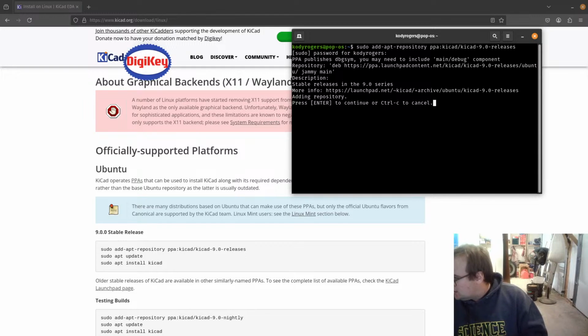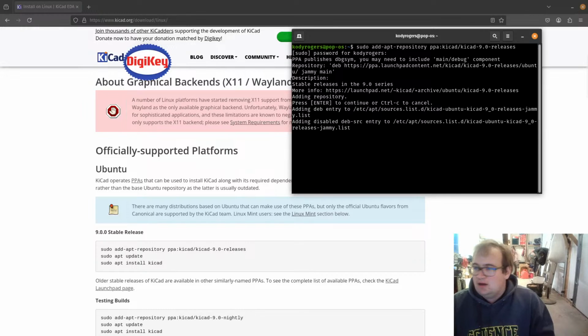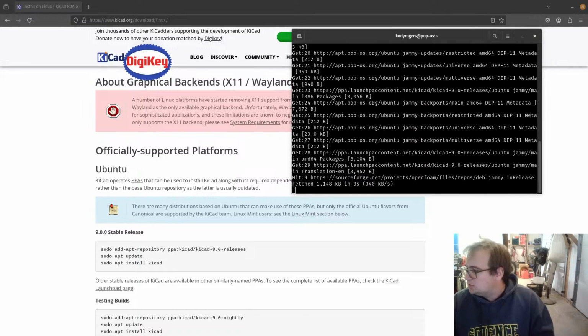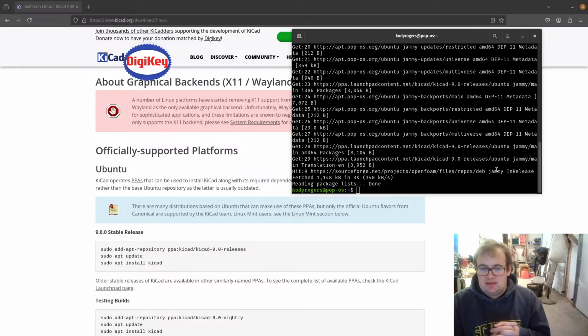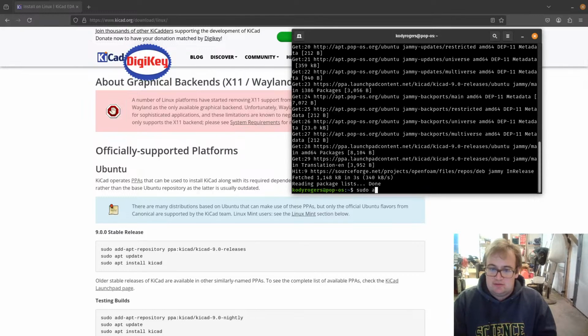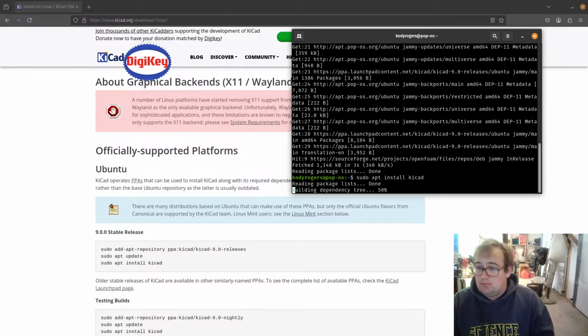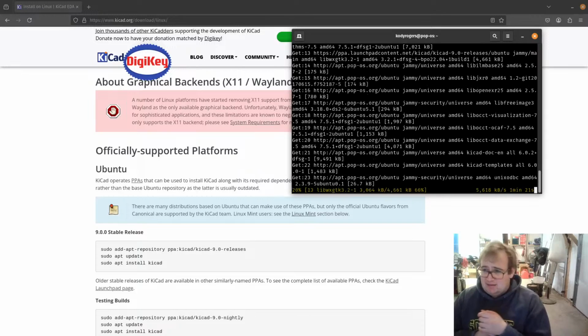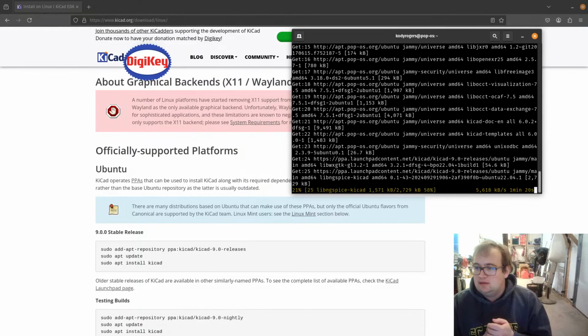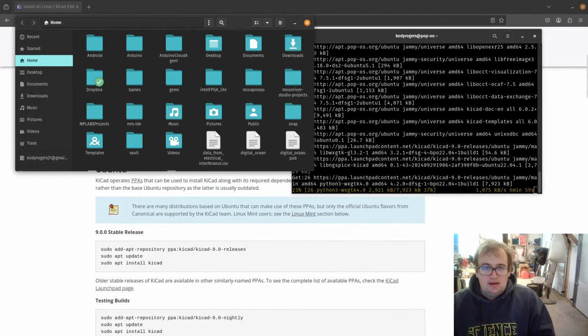What would be your doubt in creating PCBs? Like in KiCad, I'm not sure if I would be able to help, but I do know in KiCad, you make the schematic, and then you go from the schematic to the PCB layout, and then from the PCB layout, there are different plugins you can use to automatically use the KiCad files, but the more common and standard way is to generate Gerber files, which I can show later in the stream, as I am going to install. Well, it says it will take a minute.